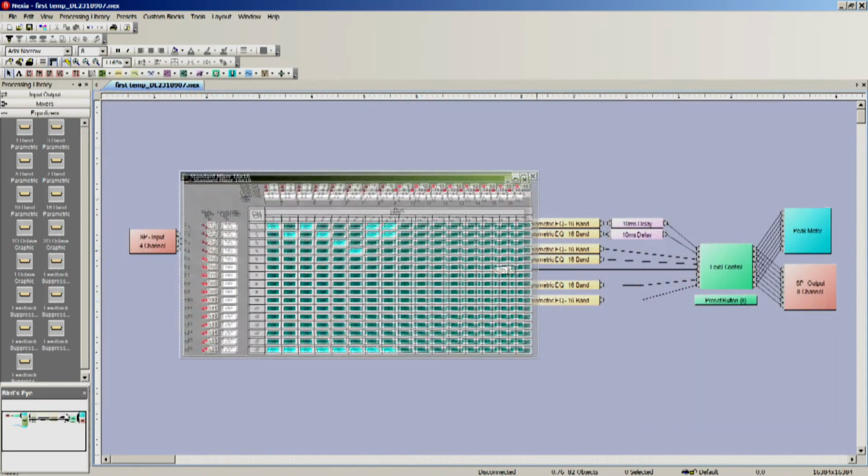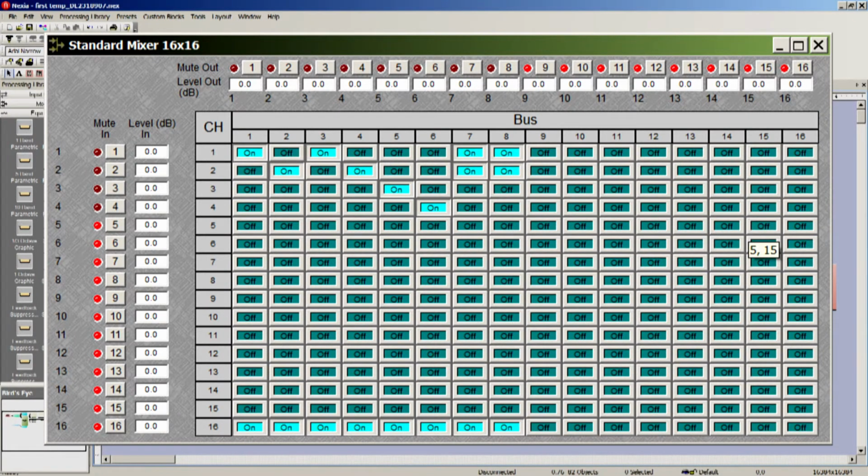Following, the signals are fed into a matrix mixer where the signal is routed for the different processing lines and outputs. Input 1 and 2 of the NEXIA matrix go to output 1 and 3 for left channel, 2 and 4 for the right channel of the Neumanns and the Visonic speakers. Output 7 and 8, sub and mono, have both signals left and right. Input 3 and 4 of the matrix go to output 5 and 6 for the headphones.